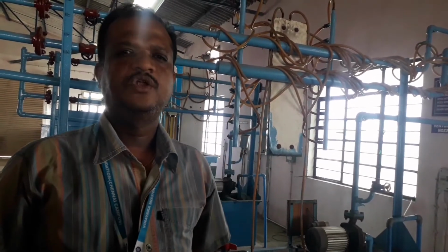The frictional losses are referred to as major loss, denoted by h_f, while losses through pipeline fittings, etc., are called minor losses, denoted by h_m. Together they make up the total head loss, denoted by h, for pipe flows.